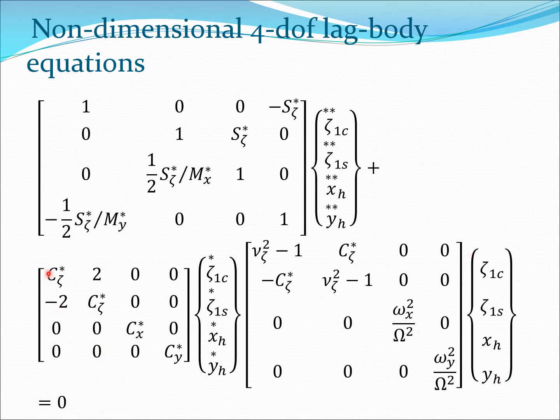Of course, we see the damping matrix, we have all the diagonal terms here, and then we have the Coriolis term here, the negative 2 term, and here also we can see some of those type of terms present. Now, this equation is going to become very important, as we will see later, and of course this equation currently sums to 0 because we have not considered any aerodynamic force as such. Remember, ground resonance is a mechanical instability.